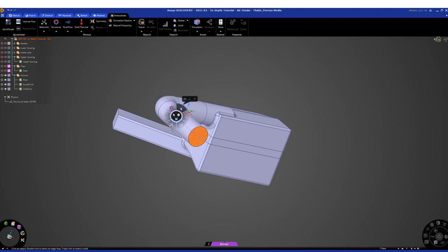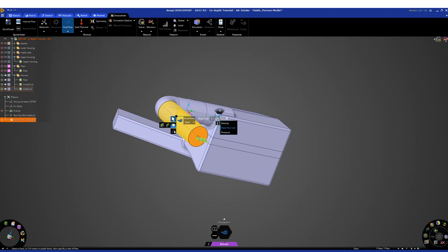Now I'm just selecting this fluid analysis, and I'm defining an inflow condition of 0.1 kilograms per second. So I'm just pressing OK here. And you see that this physics tree shows up here with all the boundary conditions of the walls and the inlet and outlet.